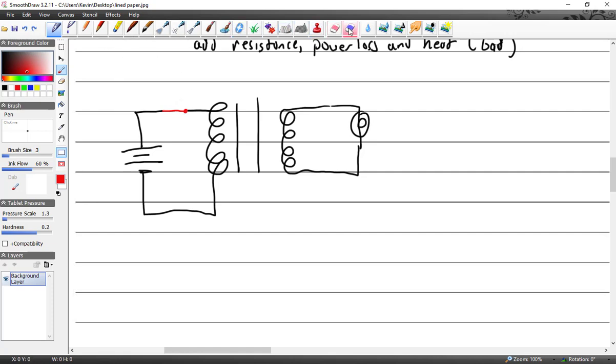Now, if we open the switch, the field is going to collapse. It takes how long? 5 time constants. But it's going to collapse pretty rapidly, right? And a rapid, fast collapse of that field that had grown across the secondary is going to induce a voltage over here. It's like a magneto. So it's going to induce a voltage over here, and the light will shine for a brief moment in time. About 5 times 5.